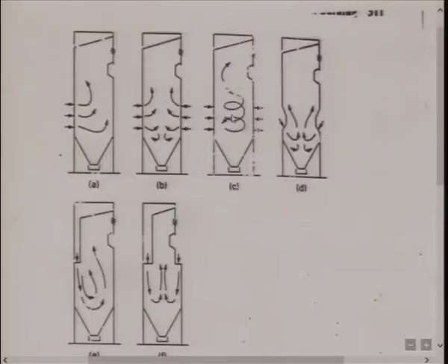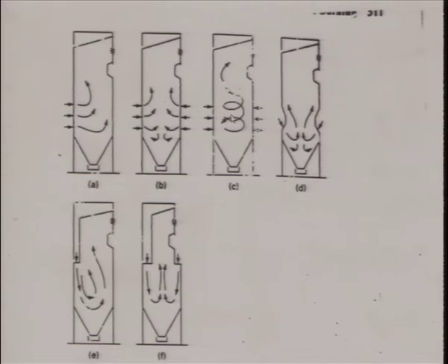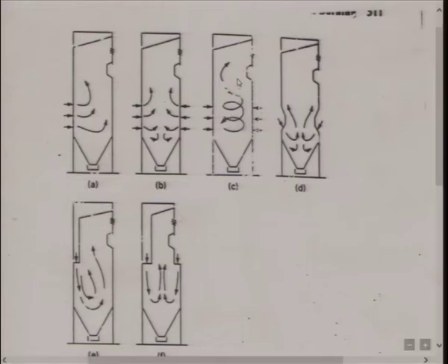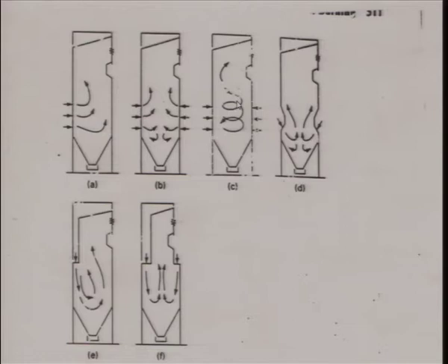This plot still shows you that because of this tangential firing, you are creating a lot of turbulence and a vortical structure, a vortex sort of structure, in the center of the burner. What does that do? It creates very good mixing for the coal and air particles, and it also lets the coal particles move like this and mix and burn, thereby increasing the time.